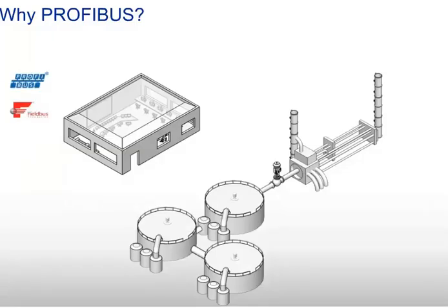Bus technologies such as Profibus and Foundation Fieldbus provide a high plant flexibility and expansion capability. All you have to do for wiring is directly connect a field device to a free T-junction in the plant, and that's it. No new connection lines to the distributed control system or additional I/O boards in the control room are required.